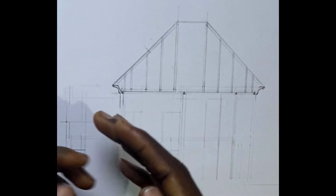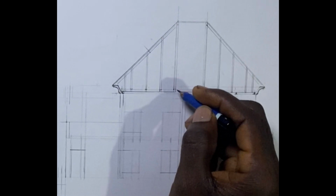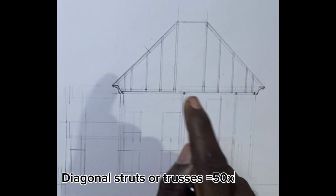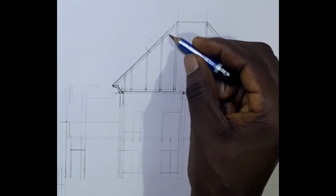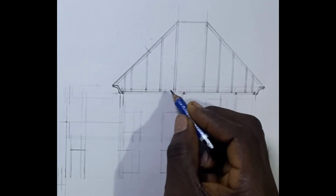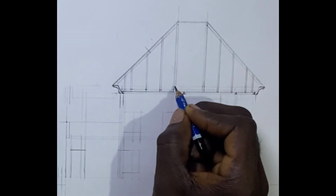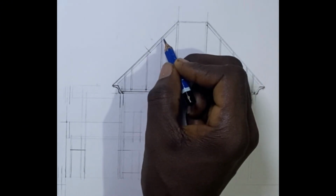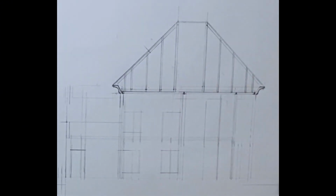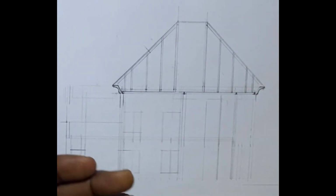Do ensure that the diagonal struts are nailed to the front of our rafter and our tie beam, and they are nailed in such a way that they are laid side by side to both the vertical king post and also the vertical strut. Why? Because we can't have three of them being joined together.